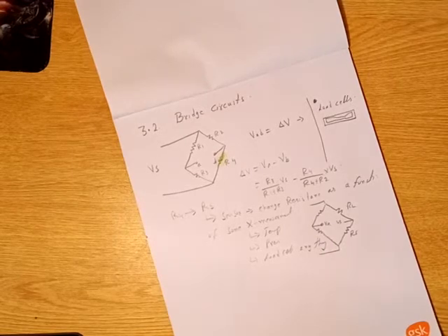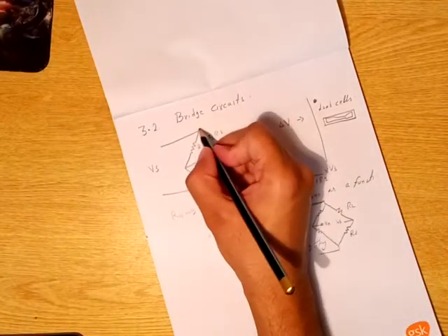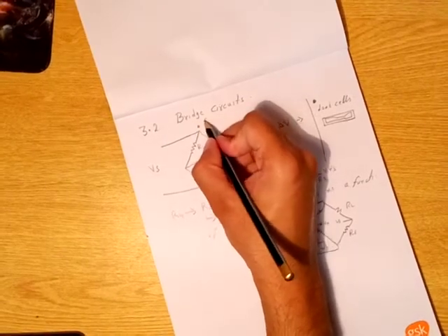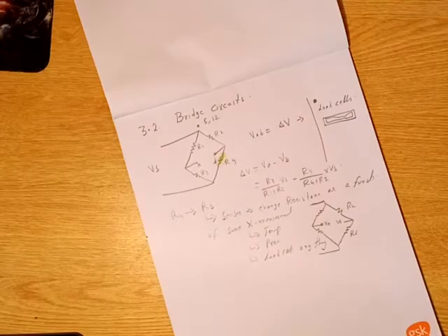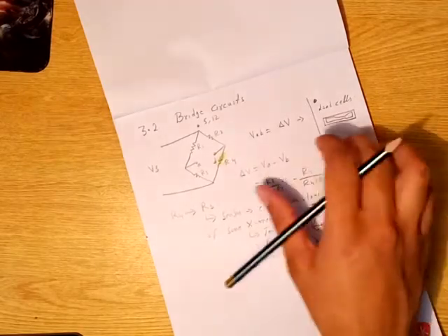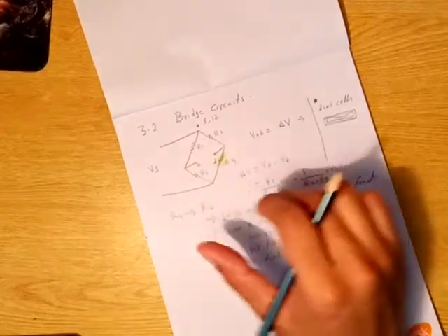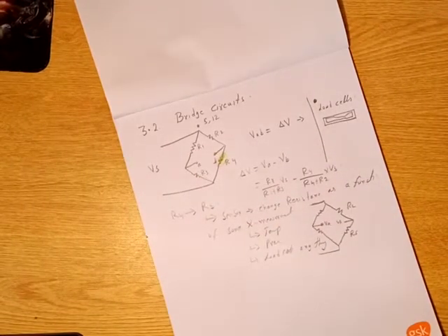अच्छा, point of difference. Point of difference is कि in this case मेरे पास सप्लाई वोल्टेज जो है इट इज़ वेरी स्टडी, ठीक है. यहाँ पे दिस थिंग दिस इज स्टैंडर्ड 5 वोल्ट्स और 12 वोल्ट्स जो आपको चाहिए. बट यू आर इंटरेस्टेड इन इज चेंज ऑफ रेजिस्टेंस. मैंने पहले ही कहा था एनालॉग सिग्नल कंडीशनिंग इज समथिंग दैट कैन किसी एक इनपुट को पकड़ूँ मैं और उसे अपनी इनपुट के साथ इंटरफेसेबल बना सकूँ. मेरे लिए इंटरफेसेबल चीज़ ये कि आउटपुट शुड बी इन सम डिटेक्टेबल फॉर्म. खाली चेंज इन रेजिस्टेंस को मैं सिस्टम के साथ इंटरफेस कैसे करूँ? आई हैव टू कन्वर्ट दैट चेंज इन ऑफ रेजिस्टेंस इनटू अ चेंज ऑफ वोल्टेज दैट इज़ मेजरेबल.